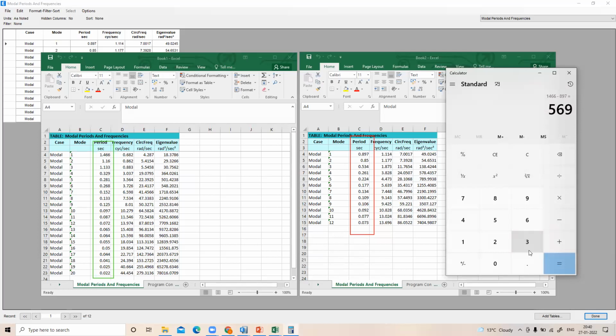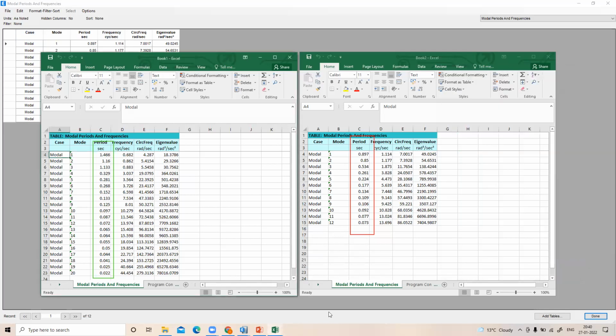Again, if you see the second mode and third mode, basically we have to check all the modes. If you have a high-rise structure, you can check for the first three modes. So for the first three modes, you can compare the structure's time period and frequency, f equals 1 by T by that formula. So you can again see the frequency and time period. These are some of the basic outcomes of this structure. That's why we need to develop this kind of structure for better performance, right?